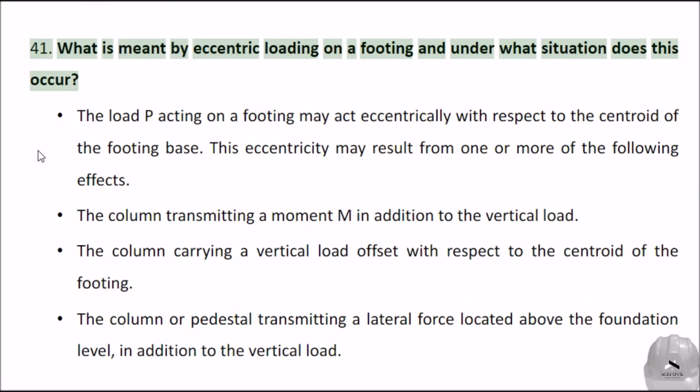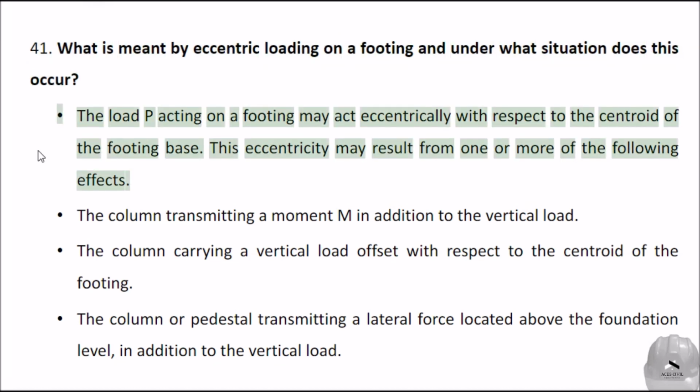What is meant by eccentric loading on a footing and under what situation does this occur? The load acting on a footing may act eccentrically with respect to the centroid of the footing base. This eccentricity may result from one or more of the following effects.